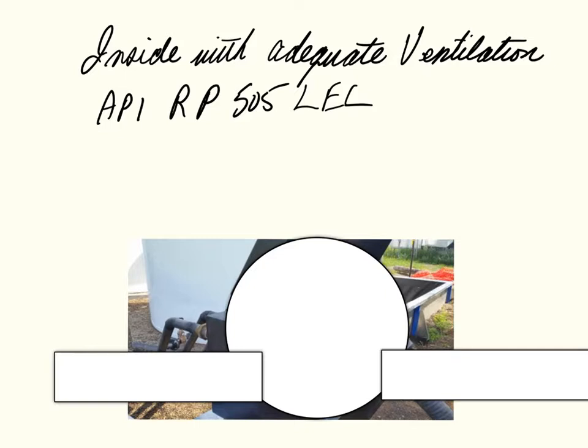And all they're getting at is that we want enough air to dilute the gas so that we don't have a hazard. Keeping enough air mixed up with the gas will keep it below the lower explosive limit. The problem with not doing that is that if you don't have enough air, you have the potential for an explosion. So the zone breaks down like this.